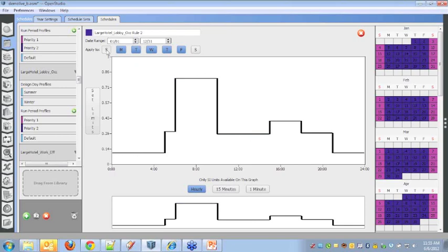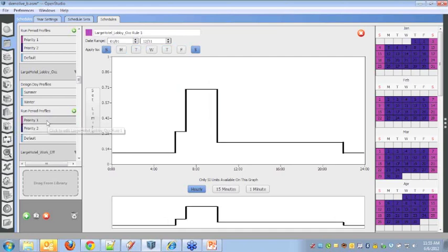So this is also operating just Monday through Friday. The blue colors tell you when this rule was applied, and this one runs from January 1st through December 31st. But for example, in a school environment where you have different occupancy and operation in the summer, you can change this to just run certain times of the year. Now on the right, you see an annual calendar, and you notice you have this darker purple and then this pink color. Those correlate to these rules. So this priority 1 rule is what happens on Saturday and Sunday, and you have less occupancy. And so that's occurring where you see it on Saturday and Sunday throughout the entire year.